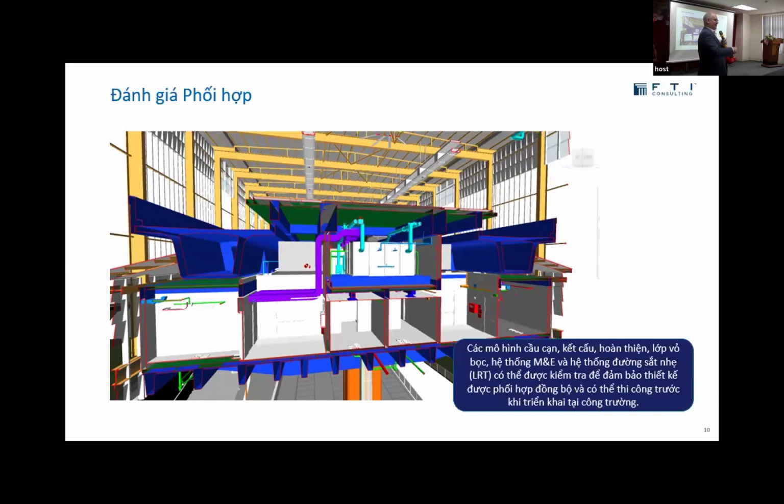So you cannot rely on the architect to do it because they don't coordinate mechanical systems. You cannot rely on the structural engineer to do it because it's not their responsibility. So somebody in an MRB has to drive the coordination. And this is where you have to start thinking about your contract. Who do you make responsible to do the coordination management? Who do you make responsible to check that all these models, when they're put together, fit together? So coordination is a very, very, very important thing.